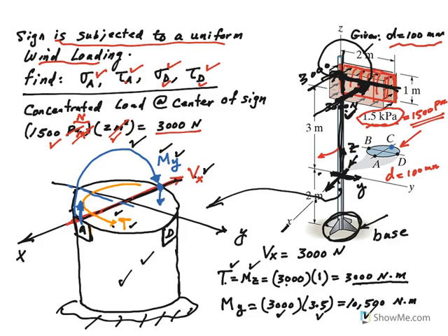But anyways, it would have caused compression, exactly the same stress, but in a compression sense. Okay, but look, point D is sitting on what? On the y-axis. So it's right here, y-axis, this is moment about y-axis. So actually, that's a neutral axis. So the stress sigma at D due to this m sub y is going to be 0.